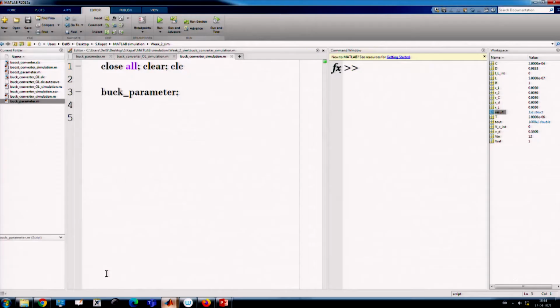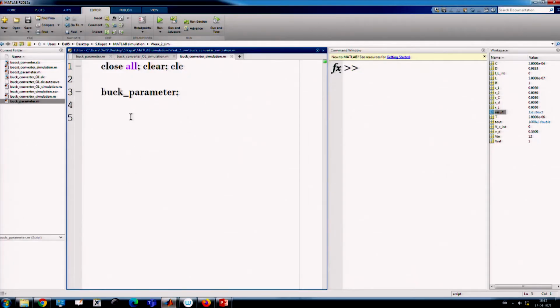Now, we want to take this data, it is there in the workspace. So, we want to create t equal to result dot time, that is our vector that we have discussed, that the structure consists of one time vector. The other, signals, is again a structure, and each signal structure has different values, like different channels.